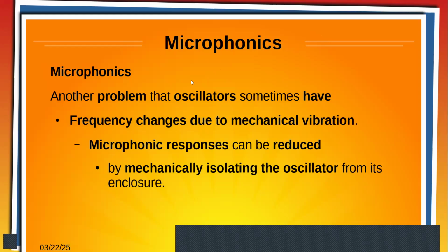Okay, microphonics is apparently another issue where physical vibration can affect the oscillator frequency. I can see that if it's a quartz Pierce oscillator, vibration might affect the crystal frequency a little bit or modulate it. If it's got an LC and an inductor, depending on how the inductor's made, it could change the inductance.